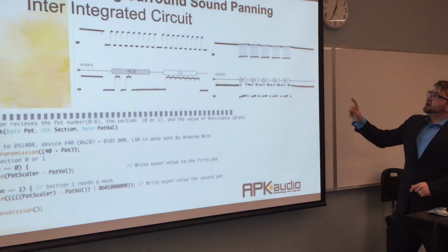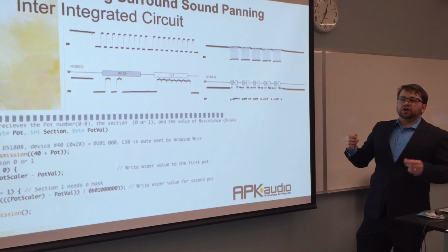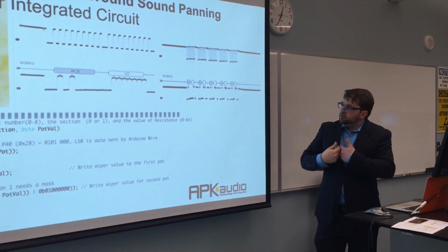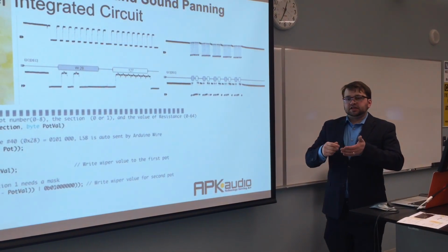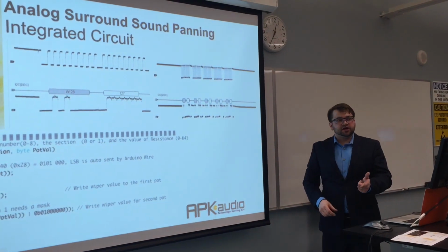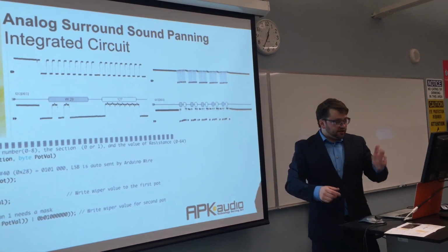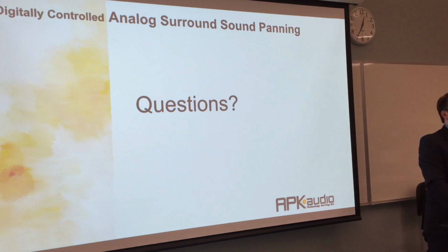Problem with this, clock noise is everywhere. So if you let it constantly poop out data, noise in the audio stream. So when I make a change of the fader, it asks, has there been a change made? And then it sends the data. Because as I was moving it, or as it was constantly sending data, you could hear it through the speakers. And that was no good. That's how it was done.